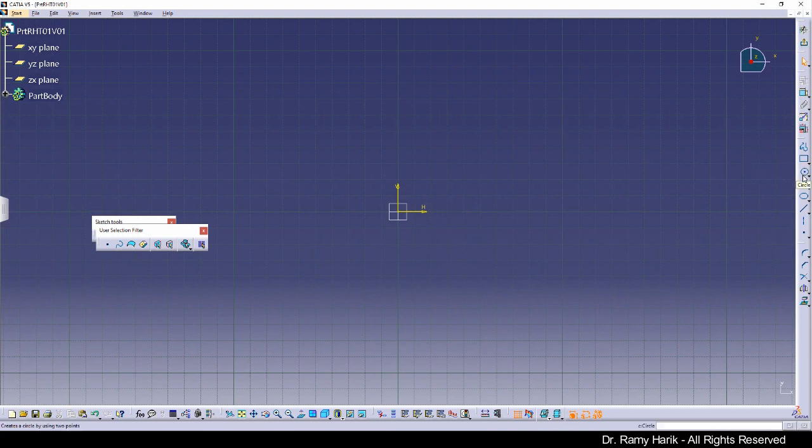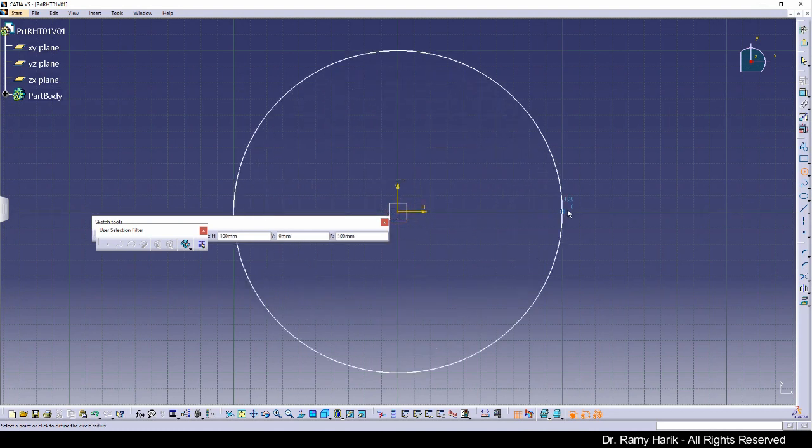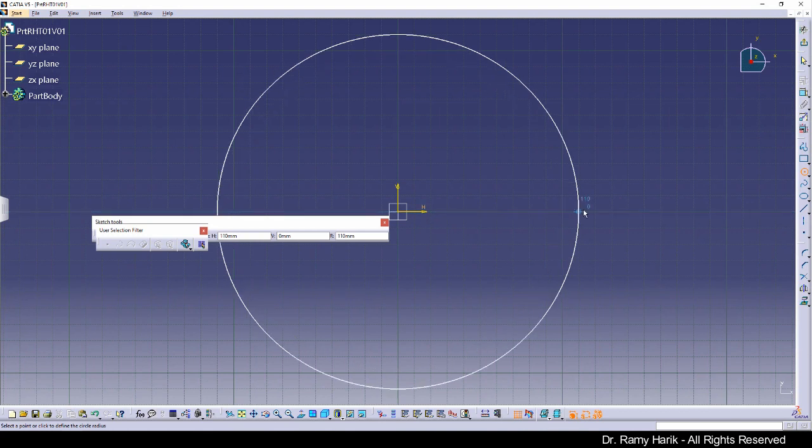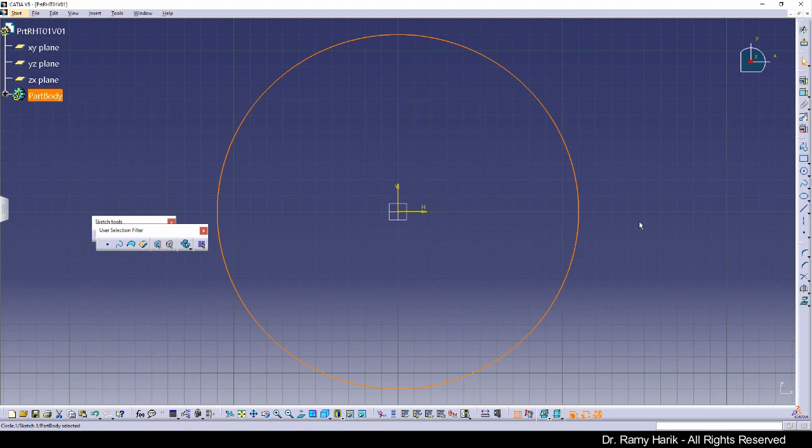So I'm going to click on the circle icon. As you can see, I'm gonna move to click on the middle so that I select the center of the circle, and to create 100 millimeters, I'm going to demonstrate it by creating a 110 and then adjusting the dimensions. So, in order to have the 100 millimeters, we're going to come in here, click on Constraint, and click the circle again. And it's going to create for us, and it's going to show us the value.